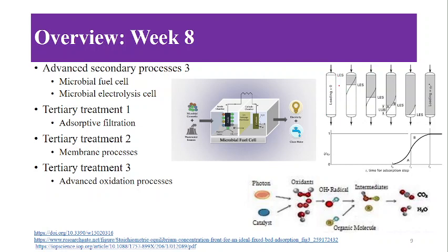As the wastewater is passed through this column, we see that the mass transfer zone increases and moves towards the bottom. And as the leading edge of the mass transfer zone reaches the bottom of the column, we call it the breakthrough point. And based on that, the different design aspects are discussed.